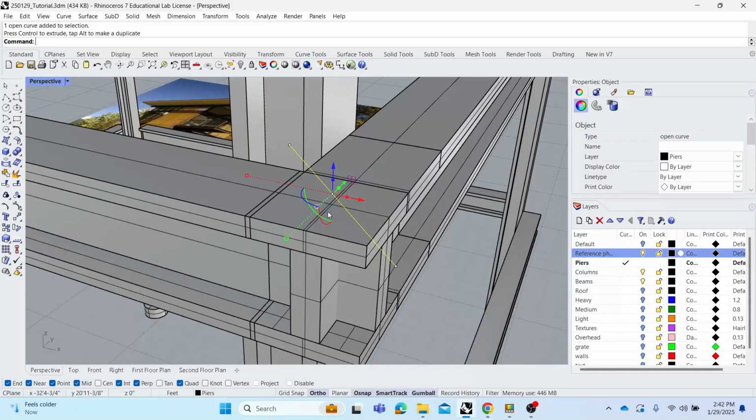If we're working in Rhino, if you get the tolerances too close, then it sometimes misunderstands what you're trying to do. So if we just make sure it goes past a little bit, we're good. And similar to what we did when we were drawing the plans, when we had a line that crossed over where it wasn't supposed to, we can trim and split. So that's what we're going to be using for these 3D objects as well. Except if we use trim or split on 3D objects, then it will just cut them away and it will no longer make them closed polysurfaces. They will no longer read as solid.